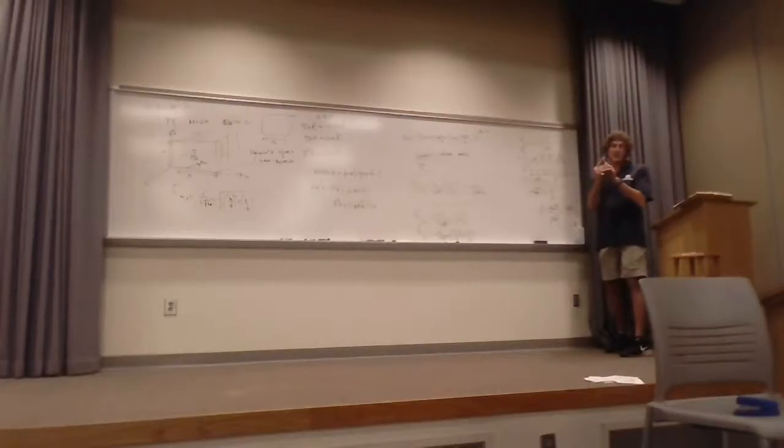Now, how big is 30 centimeters? Well, a meter is about that long, right? A third of it is about that. That's a wide waveguide. A gigahertz is a very low operating frequency. Now, at 10 gigahertz, a half wavelength is about that. Y'all with me on that? And you start understanding about dimensions just by looking at the cross-section of the guide.